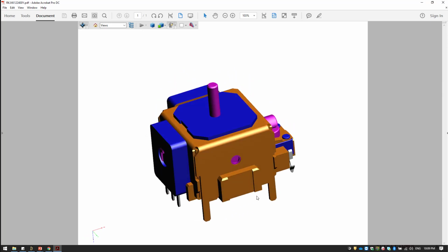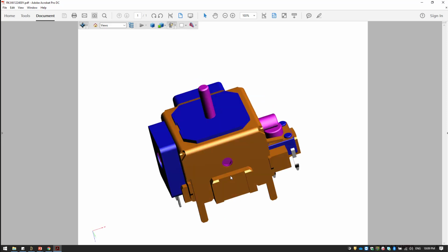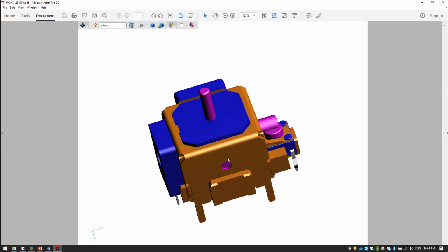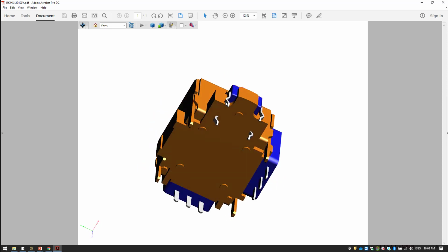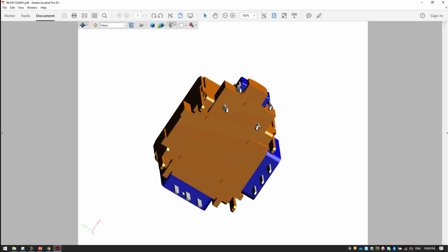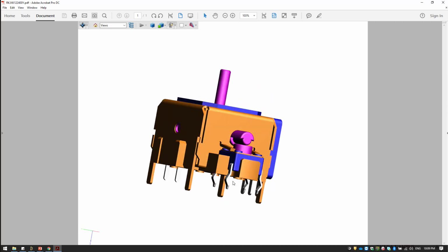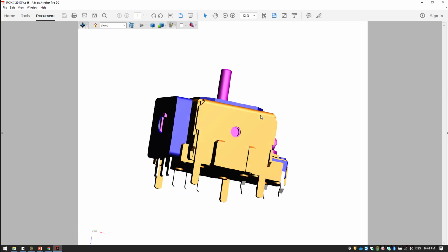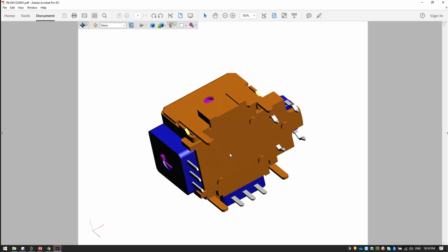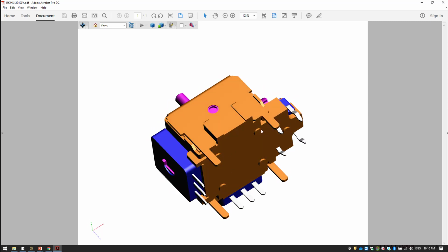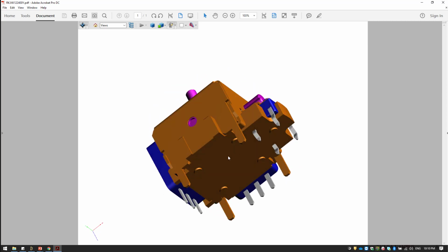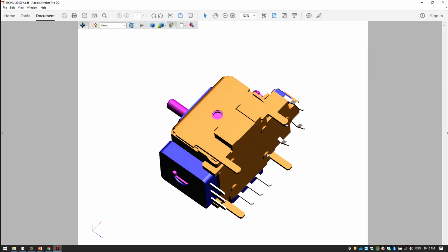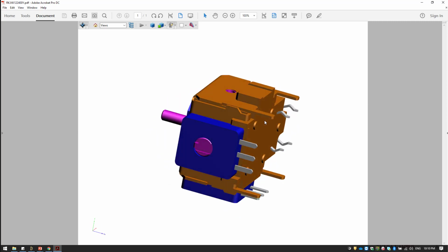You don't want to break the pads or the board when you push or move the knob. So these are good mechanical support. You don't want to put the mechanical support on these electrical pins at all, because they will break. Now, as you can see, there are some knobs in here on the bottom, and these are also part of the body of the joystick. These are mechanical features, so we need to account for them.